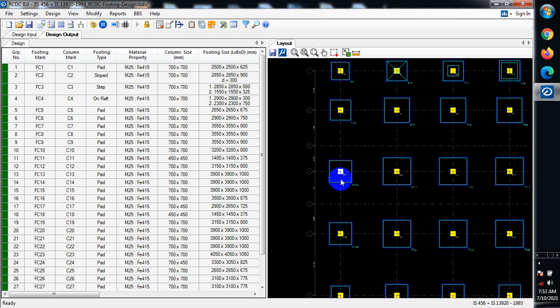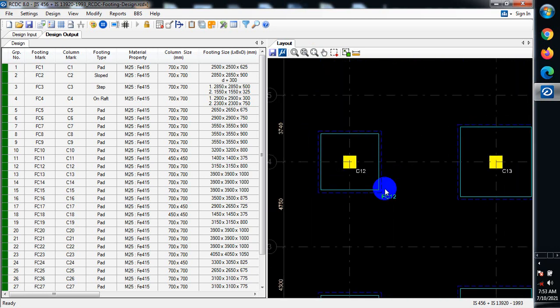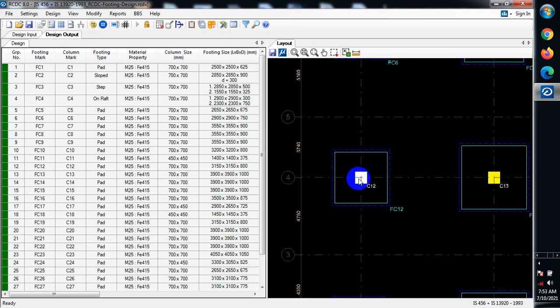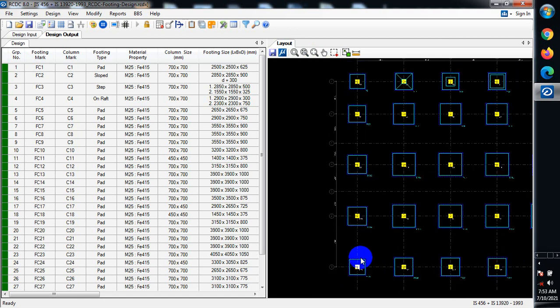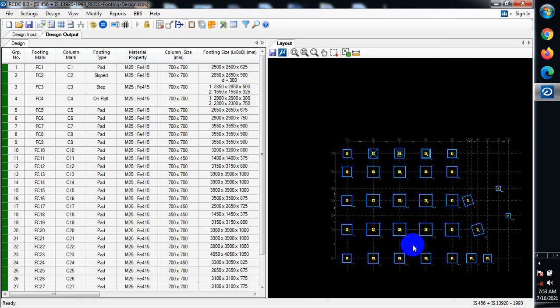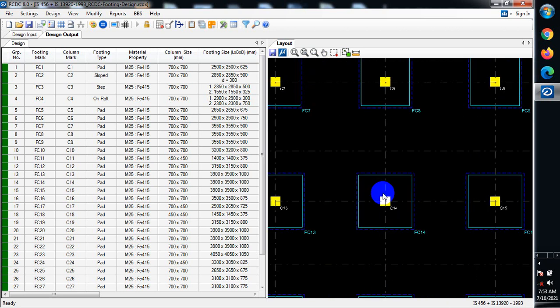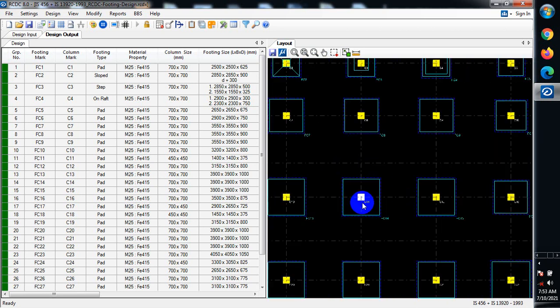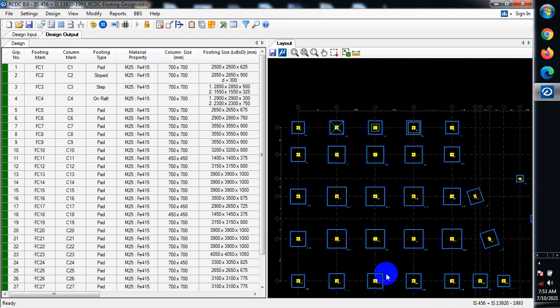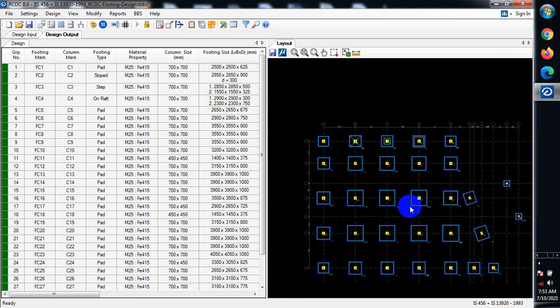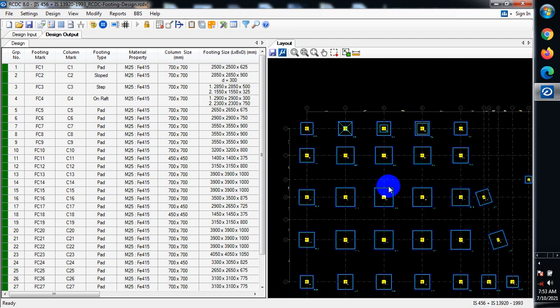So definitely, even if you discover the bases are different, there are cases where you may even have the column being of different size. If you look at the one that is actually axially loaded, which is this column 14, you can see it carries more critical load than any other column in your design entirely. So this column is carrying a more critical load. These and these are kind of identical, they are carrying similar load.